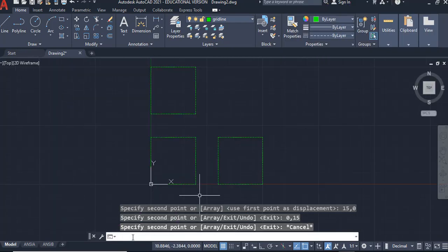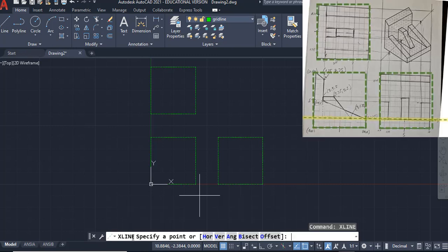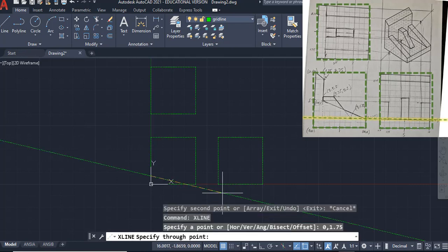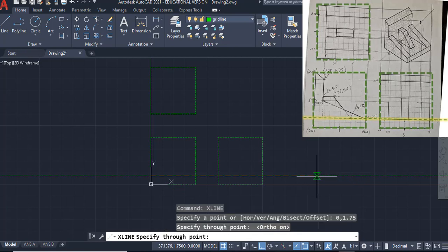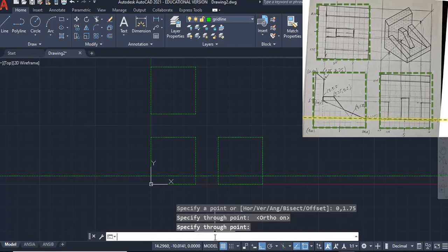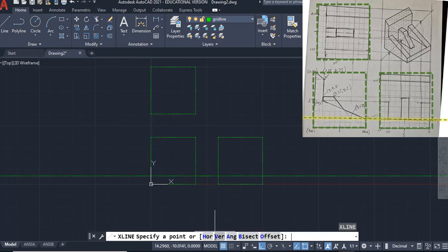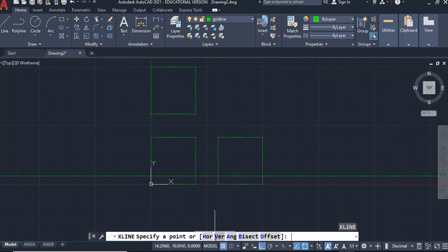And the next thing I'm going to do is put some X lines in where we have features on this thing. So we have lines at, let's see, we decided, and this is just an estimate of where those were coming across. Now right now it's kind of hard to snap that across, so I'm going to put on my ortho snap, and that'll let me get a nice perpendicular line. So we'll leave that for our first one. Enter brings that up again.